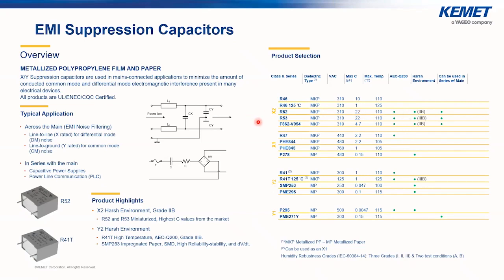And for the electric compressors, we know that the stress on the capacitors is related to their position in the compressors. That means if the inverter is placed outside of the compressor, in this case, the capacitors may endure high environmental condition stresses. Whereas if the inverter is integrated within the compressor, since it's hermetically sealed, the capacitor won't see high environmental stresses, but the miniaturization is still needed here.